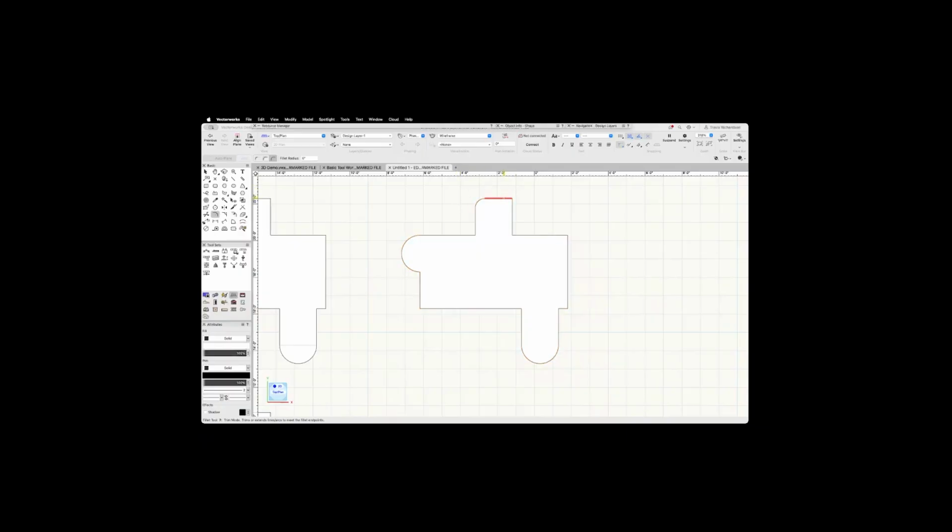So I'm going to continue around the perimeter of this drawing. I'm going to go from the horizontal to the vertical. Great. And just going along the perimeter, doing all of my 90-degree corners so that all of those are soft and rounded. Great. Once I'm done with that, I can hit X to activate my selection tool and click on empty space to deselect that polygon.